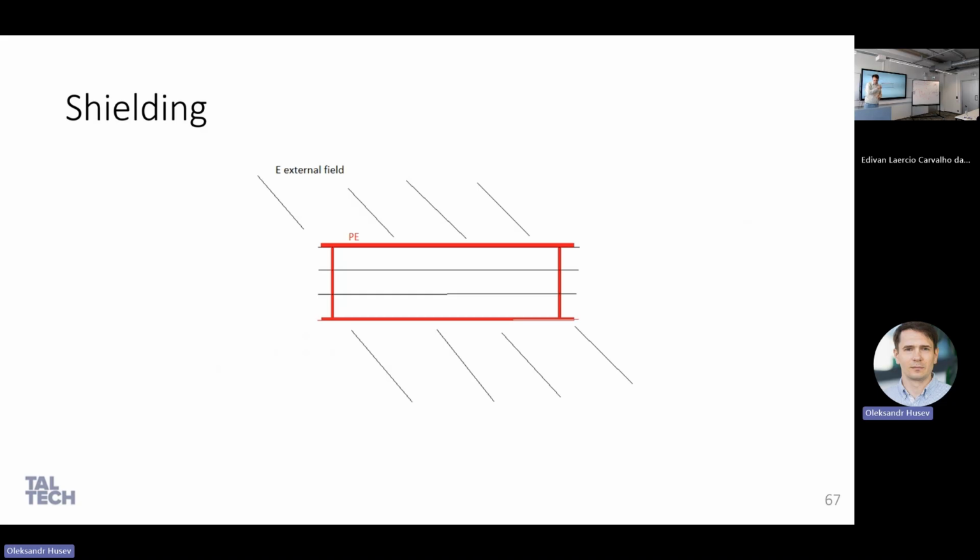So if you pay attention, I will show also some examples. In our PCB designs, we always have copper. If it's not used, we keep it as something like protection earth, not connected directly, but we can use stitching vias to make it a shield. It's an immunity issue because it protects from an external electric field, or maybe, for example, an electromagnetic wave created by an inductance near the PCB, right? But all copper should be useful. And this is one of the examples.